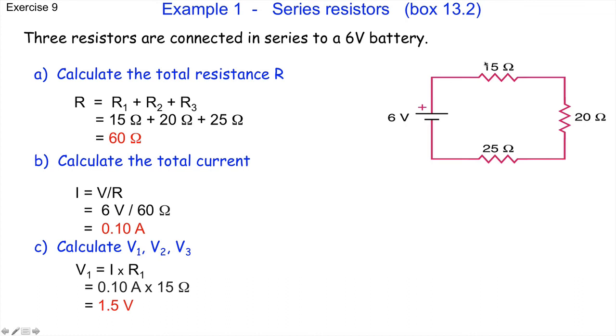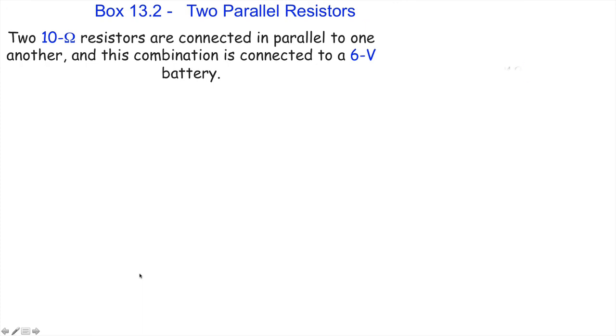Then how much voltage is dropping here, how much potential difference is dropping here? You find it by multiplying the current and the resistance. Where did we get that equation? In the second or third slide, when I was talking about Ohm's law being applicable at each resistor. Therefore I times R1 will get you V1, I times R2 will get you V2.